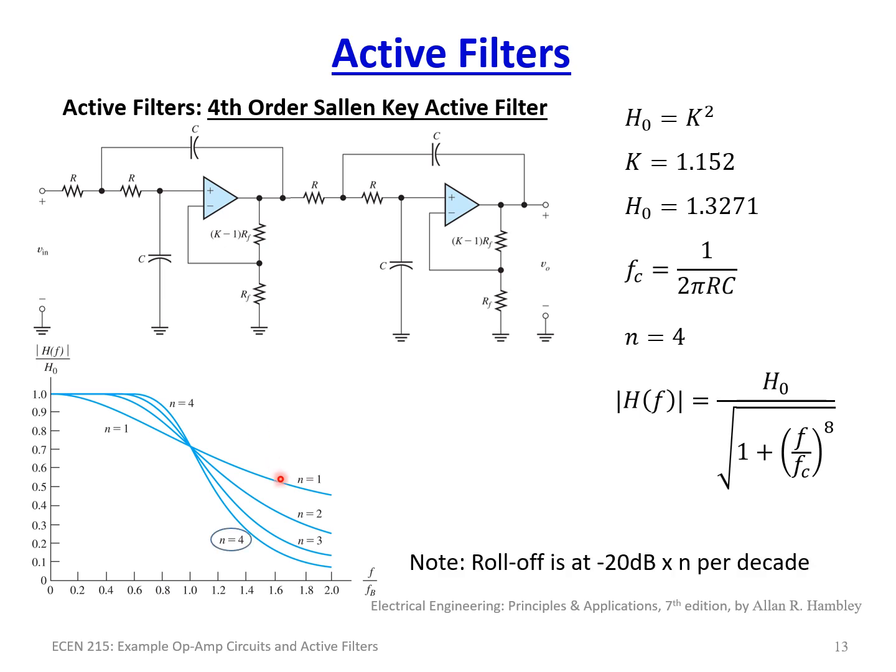And of course, the interesting thing here is that in the case of decibels, the roll off originally, per order, per N, is 20 decibels per decade. So here it's 20 times N. So if your roll off is minus 20 decibels per decade, then it's minus 20 dB times N. In this case, N is equal to 4. So it's minus 80 decibels per decade.